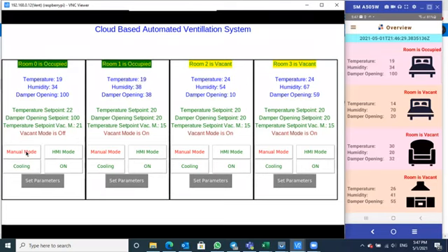As I told before, we have an on-off button. If you select the off button, it puts the room in off mode so that nothing works in this room. If you select on mode, the room is enabled. We have a cooling, heating button here. We have manual auto mode. In manual mode, only the damper opening set point works, and the damper will work by the percentage given in the damper opening set point. In auto mode, depending on whether it is in heating or cooling, the damper will be closed or opened until we reach the desired temperature.